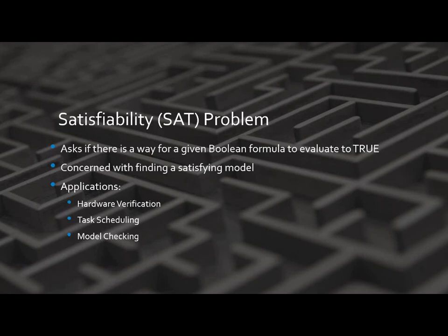And one thing about SAT solvers is they're highly efficient and automatic, because there's been so much research into the field that though the SAT problem is an NP complete problem, there has just been so much tweaking of the algorithms that these solvers use that it's to the point where they're really highly efficient. And so part of the idea behind this project was to see if I could use a SAT solver to solve that optimal control problem and generate a resulting trajectory for the robot.